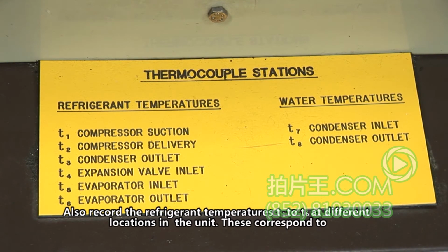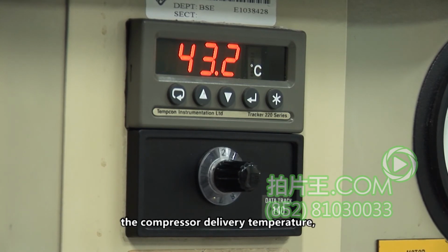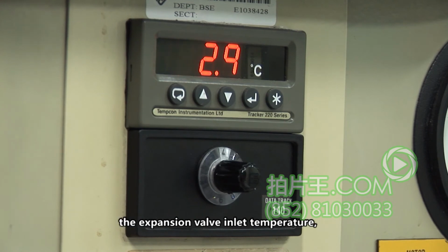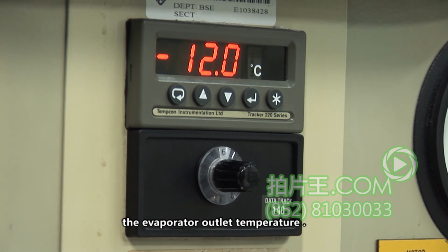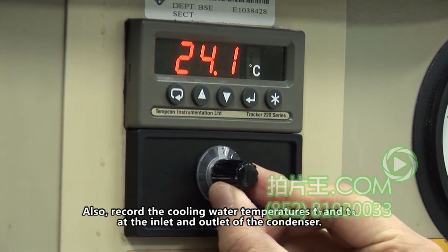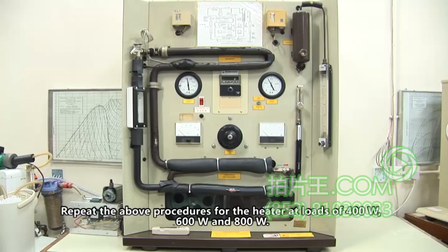These correspond to the compressor suction temperature, the compressor delivery temperature, the condenser outlet temperature, the expansion valve inlet temperature, the evaporator inlet temperature, and the evaporator outlet temperature. Also record the cooling water temperatures T7 and T8 at the inlet and outlet of the condenser.